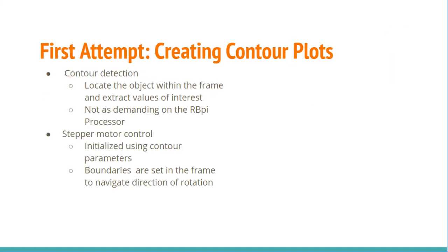Before importing data and images into our Raspberry Pi, we want to get a better understanding of how OpenCV works by initially testing color objects. In our case, we chose the color red. The video we are about to present shows a demonstration of how the stepper motor is controlled using Raspberry Pi and the Pi camera. Using the same concept with contour detection, we want to implement a similar method shown in the video to our design once we import and create a path to a pre-trained model so that the stepper motor can move depending on the location of the bottle.